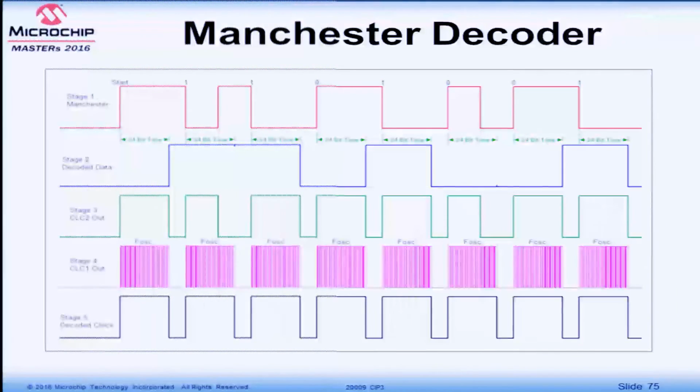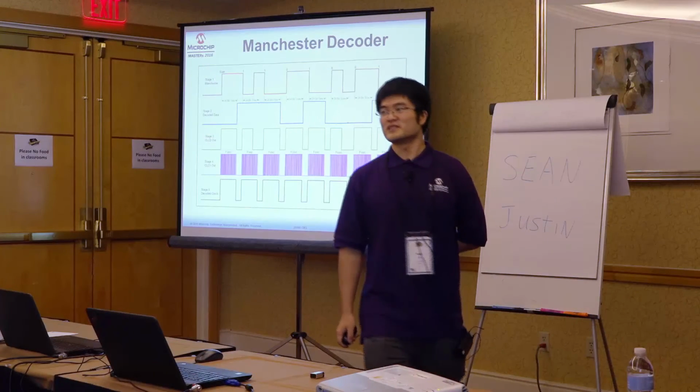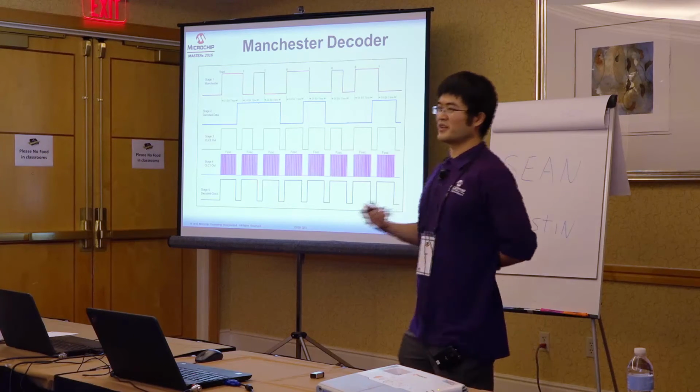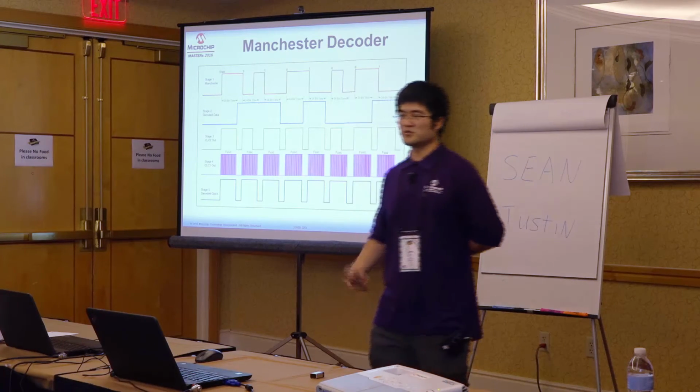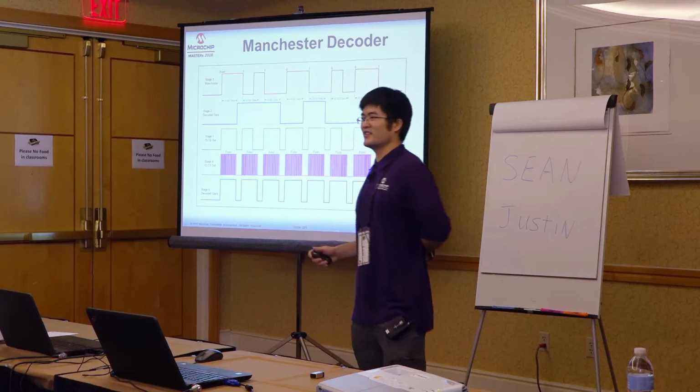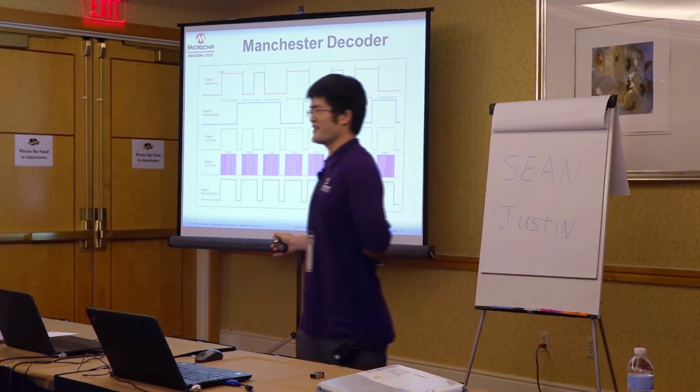All right. So again, I think I'm missing an animation here. The only caveat for this one is your first bit will be missed. That can be easily compensated by either transmitting a known first bit or just transmitting some dummy first bit in the software. So that's the only caveat here, but it's much better than doing bit banging, I hope.